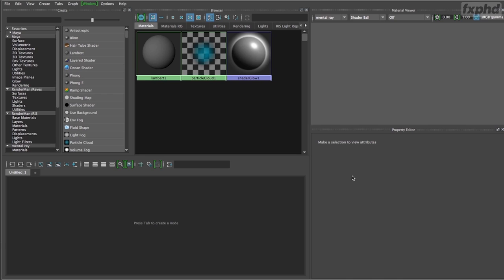It takes all the things that you need for look development and brings them all into one place for the first time. So you can do things like build your shaders in a node editing interface, and that enables you to do things like solo a single node, so you can just look at that node. You can create custom layouts of what we've got here. You can edit your material using the editor properties window, which is part of the attribute editor, which they've now brought into the Hypershade. You can work with multiple shading graphs simultaneously, and it really enables you to see what you're doing very quickly.